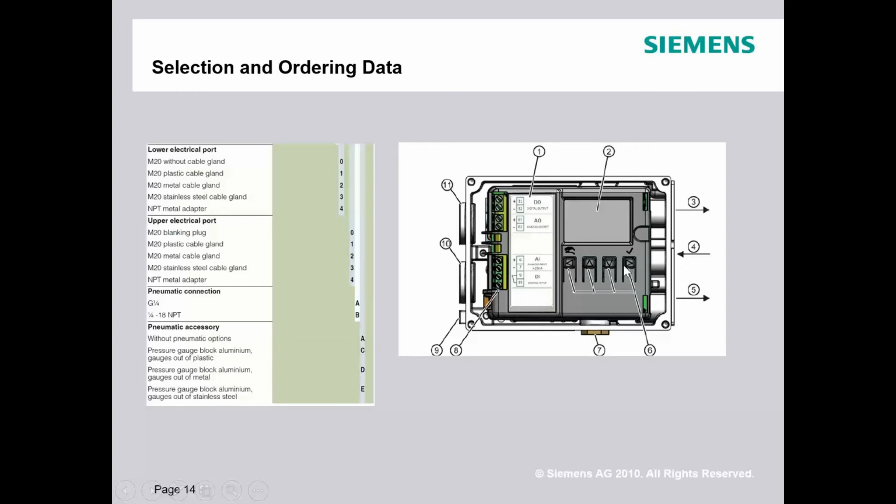One thing about all of our digital positioners, our flagship product and the PS100, is we always have the buttons. That means you don't get a blind one. You don't get one where you have to go find a handheld or a computer or something. Our flagship product, you can use that, and pretty soon when we get HART, you'll be able to use it with this. But you can always use those buttons and calibrate it. You can put it in manual and stroke it, do what you want to do without having to have any other device if you don't want to use it.